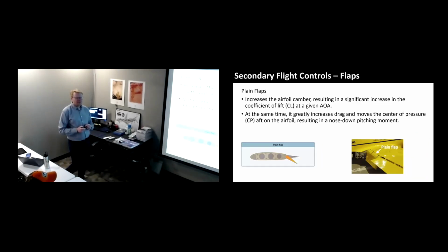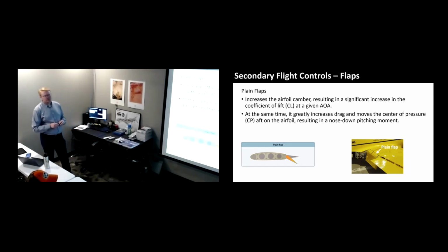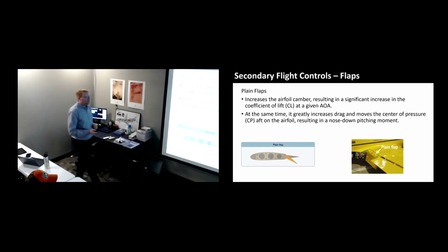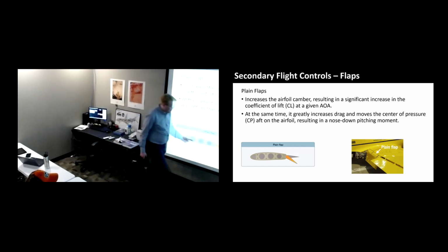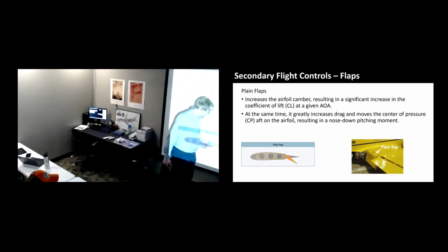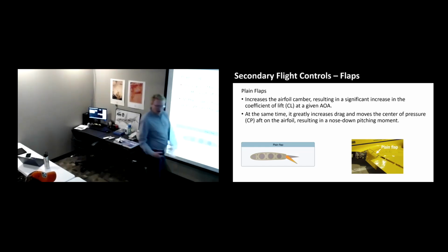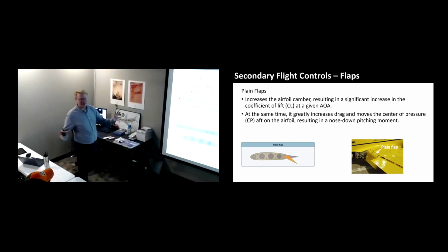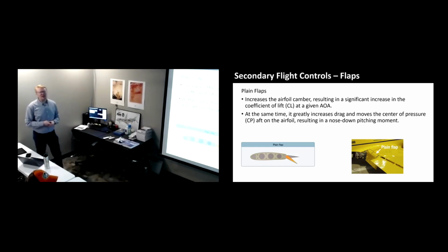Sure. If you had your flaps down and you're going into a turn, what would that do to your air? Because if that air is just not going down, it's going around that flap as well. It does, but most of this air will get trapped on the bottom and get deflected down like this. There's going to be a little bit moving around the edge, but not a significant amount, just as much as any other flap. Most of the issue here is that this air gets here, gets stuck here, has nowhere to go, so it's forced down. That causes the drag portion of it, not that it's necessarily going over the sides. Even in a turn, it still has the same force. Did that answer that? Yep.